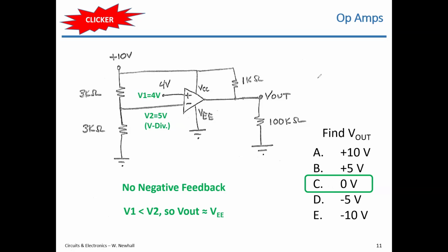Okay, so I'm going to isolate this part of the circuit. You have a 10 volt source, right? That is connected to this point right here, which has a 3K ohm resistor. That's this top 3K ohm resistor. And then I have the bottom 3K ohm resistor, right? So that's how these two resistors on the left are connected. I'm looking for the node voltage right there. This is V2. Okay, and V2 is the voltage between here and here.